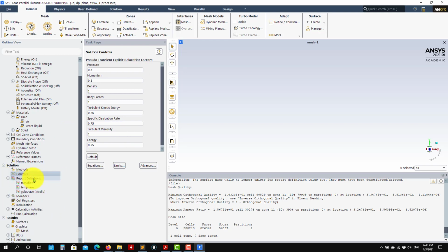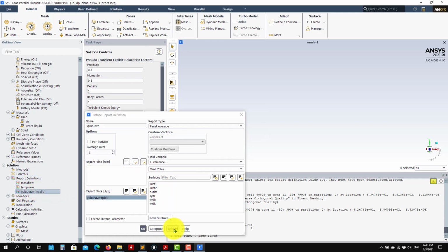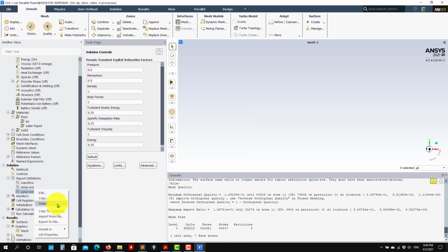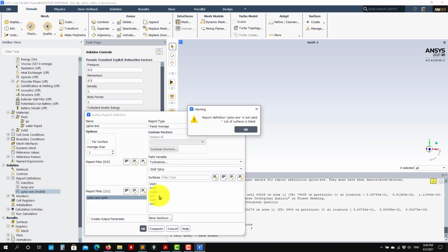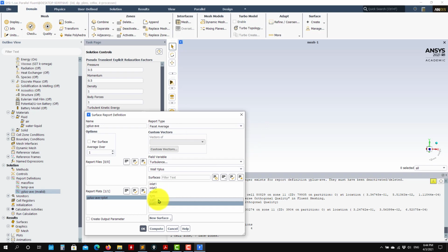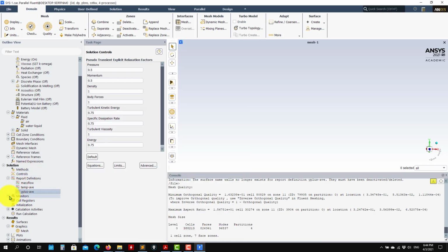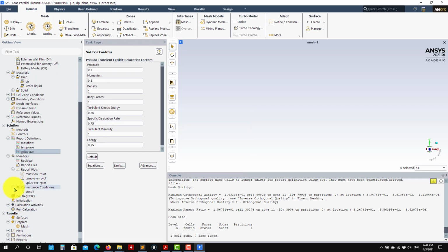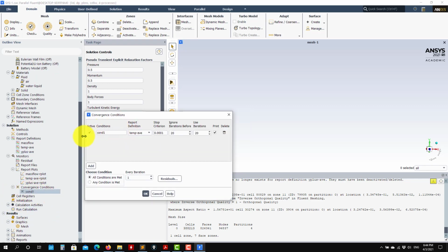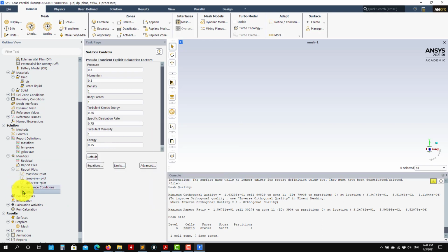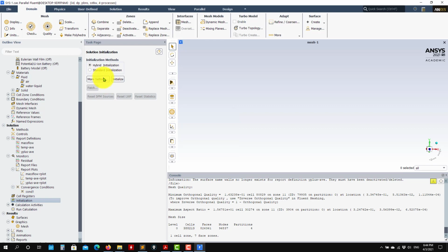And here you see that you have all your report definitions. You see Y+ is invalid because the name of the patches is different. We're using different names. So as you right click, edit, you just select the walls, the patches where you want to compute that one. So it's this and this. Control for multiple selection, okay, and now problem solved. This is okay. This is also the condition that we created, okay, so we're doing one temperature average. So everything is okay.